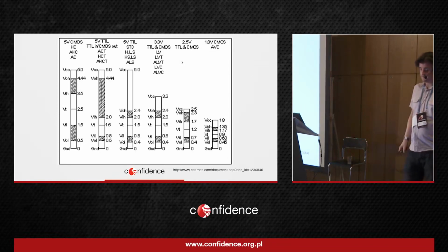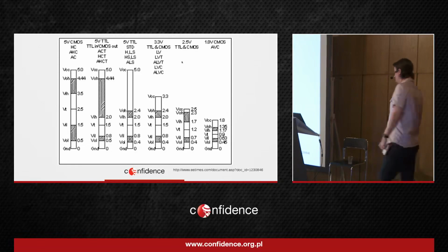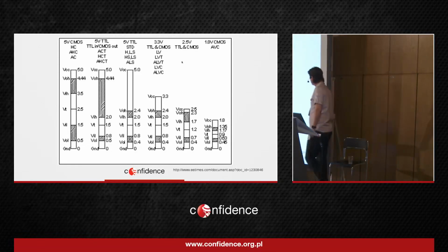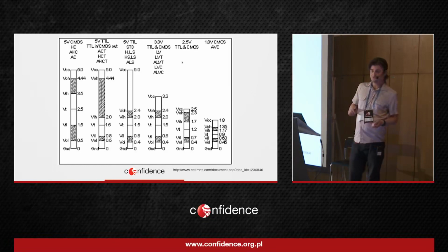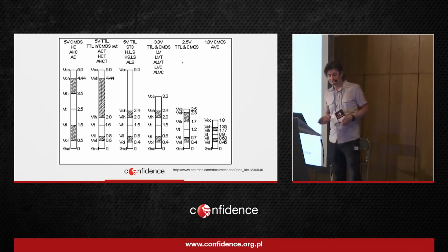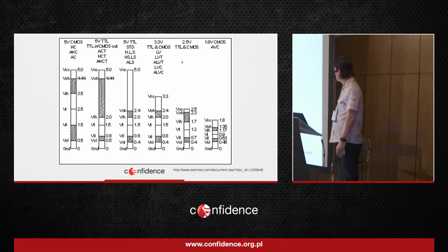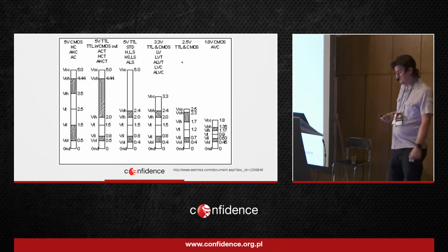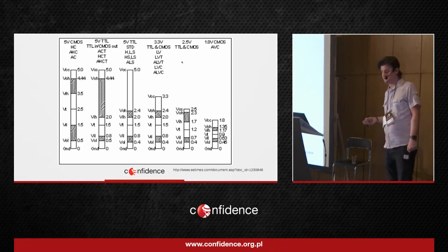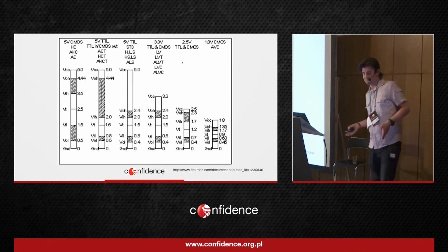Let's go to our embedded devices. We will never see 15 volts or more on our embedded. So let's have a look what voltage we can find. We can basically have two types of electric circuits: CMOS and TTL. One is transistor based, the other is MOSFET. It's not really important. What is important is the voltage level, because when you are connecting something to a system on chip, to the processor, they are not voltage tolerant. So if you connect 5 volts to a chip that has 3.3 volts, you will burn it.